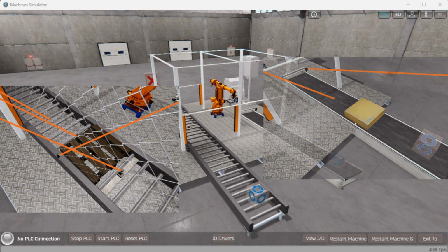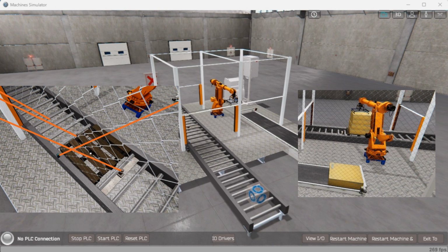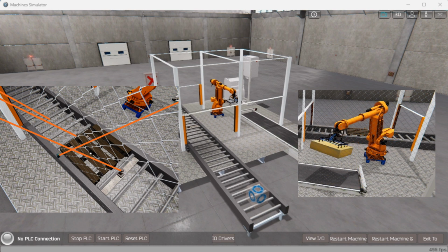The roller conveyor contains the pallets. When it is running, new pallets are created automatically. Conveyor stopper 1 will activate to position the pallet to accept boxes. Stopper 2 is used to prevent further pallets from entering the stacking location. If photocell 1 is not seen, then stopper 1 will be activated and the roller conveyor will turn on. When the photocell sees the pallet, the conveyor will stop and stopper 2 will activate.